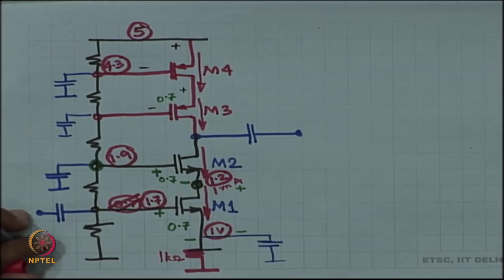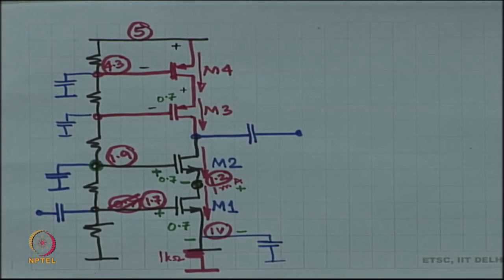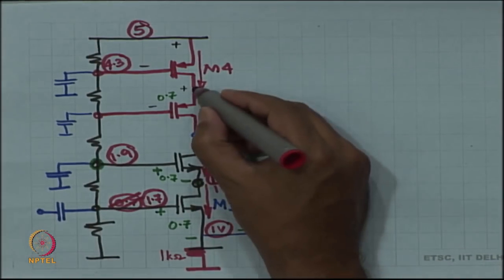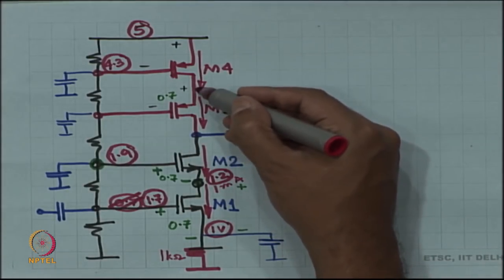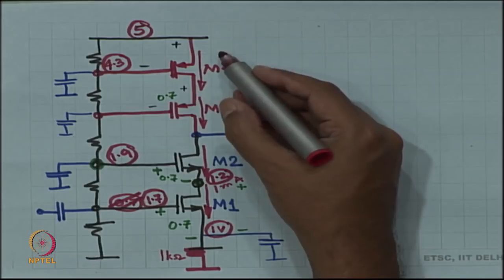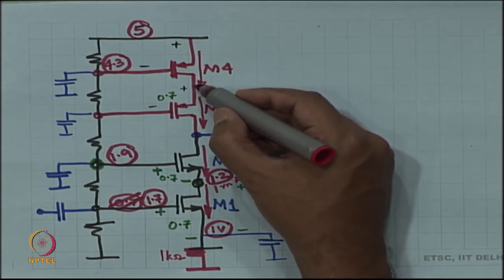Okay, so I have got 1.9 volts here, I need 1.9. How about here? So, we will have this exactly the same story in the PMOS, right. This is a low impedance node. You now understand what it means, that is the impedance looking into this node is low. So, if I have some signal current, then the signal voltage over here is going to be low.